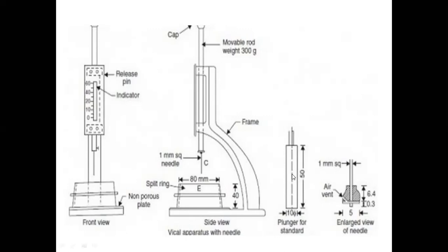and then we arrange the plunger, and drop the plunger down to penetrate. For the penetration, you have to see the reading on the graduated scale. You may see a reading of 9 mm, 10 mm or 12 mm first, because there is less water. Then we add a 2% increment, so the water is increased for the same sample.